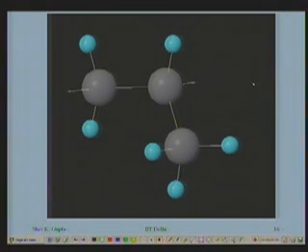And these days, with polypropylene, we draw the fibers, we spin the fibers out. The melt is made to drop on a rotating disc, and fine fibers of polypropylene are taken out. Then it is converted into staples, and you can make a thread out of it, and make sportswear. Polypropylene does not absorb water at all, but in the capillaries formed between the fibers, a lot of water can be held by surface tension, and that's why this sportswear can absorb all your sweat when you are working, running or playing.